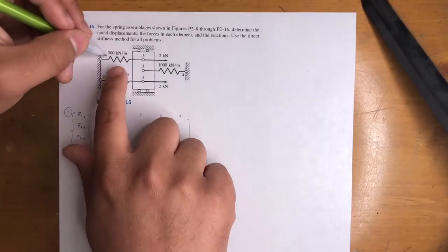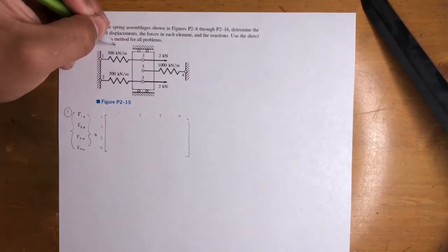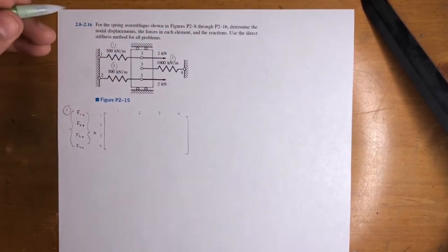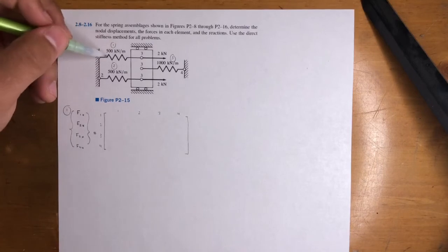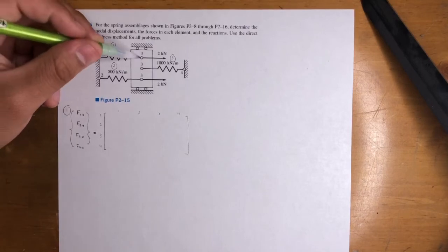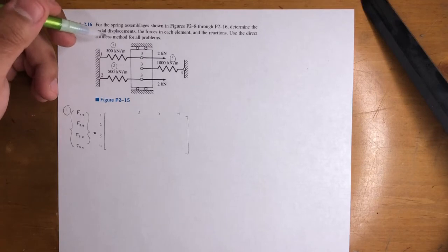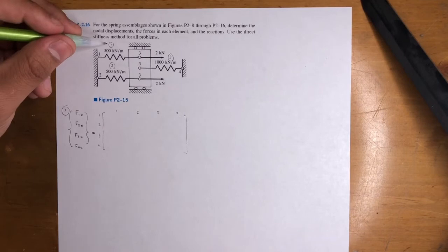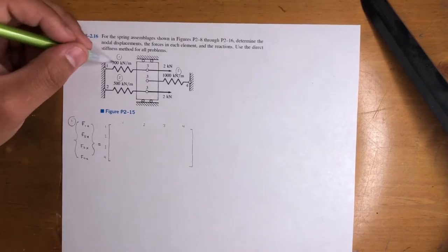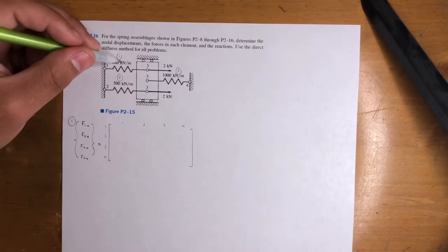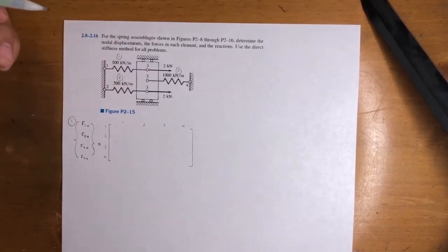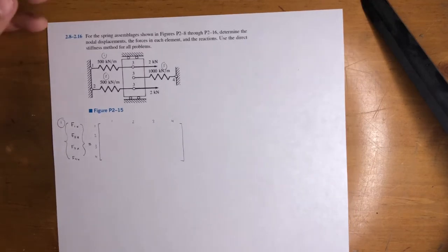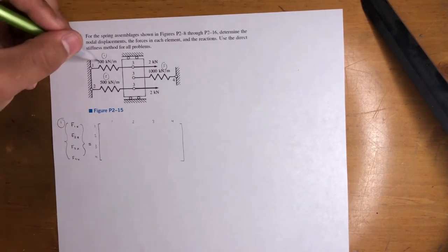So look, this one's between nodes 1 and 3. This is elements 1, 2, and 3, the spring. It really doesn't matter how you name it. What matters is what nodes they are in between, and what nodes are to the side of the spring. So in this case, let's do the first one. That is 500 as the value, kilonewtons in this case. Everything's in kilonewtons and meters. There's no reason to convert to just newtons or whatever, right? So we'll leave it 500 and 1,000, but in this case, just 500.